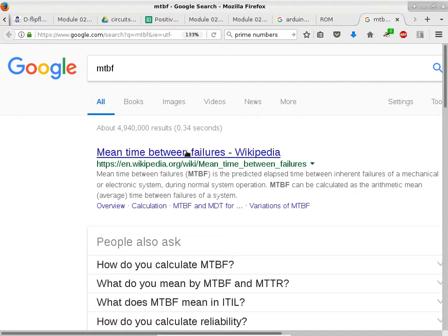Like a mechanical drive, the spindle is usually the problem, because it's basically just a single point. There's a bearing, but very few types of mechanical bearing design can handle 10,000 RPM almost all the time. So that usually is the limit. When that starts to go, your drive will start to wobble, and then things will just kind of go south at that point. You can also have particles getting into the drive.